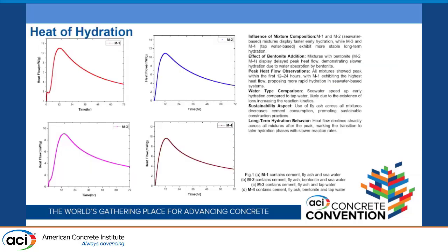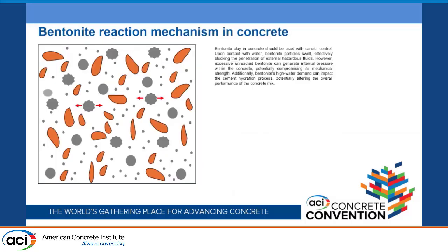Heat of hydration shows that for higher dosage mixtures, there was a slow heat of hydration because of the water retention property of the bentonite clay. However, we noticed that for the seawater-based concrete, because of certain minerals present in the seawater, there was an increase in the heat flow.